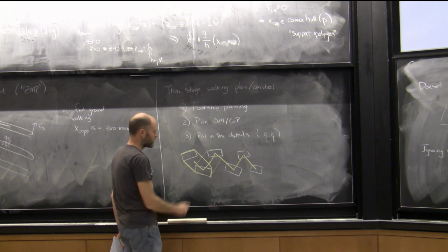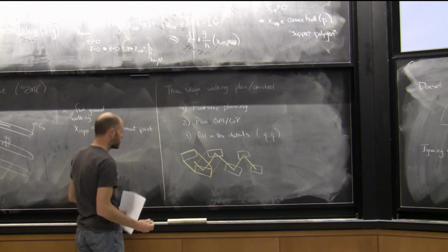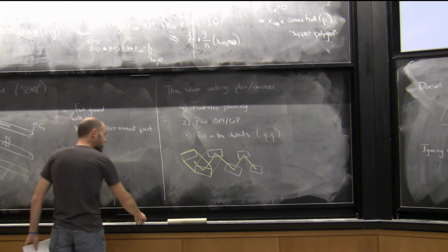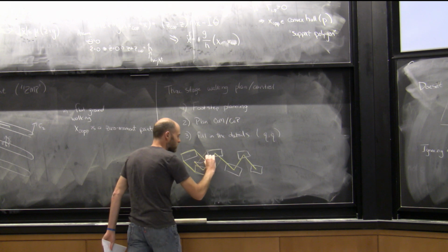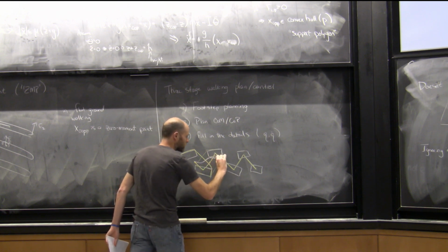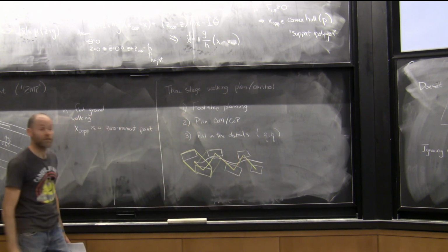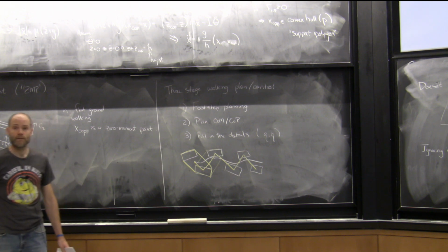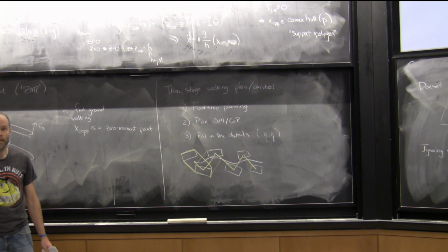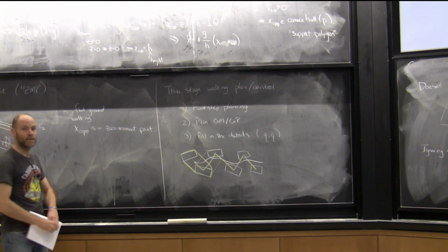Okay? And then you can just run this equation through to solve for the center of mass trajectory, which ends up doing something like this. It does not have the constraint that it's inside the support polygon, but you can solve for it exactly. Yeah? If your center of mass is not inside your support polygon, wouldn't your theta double dot be something else in there?